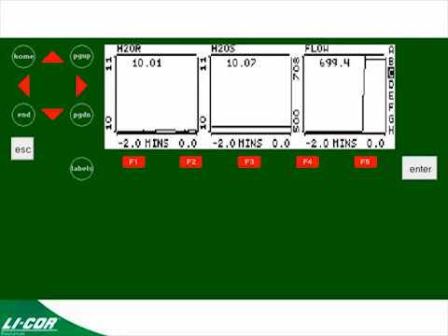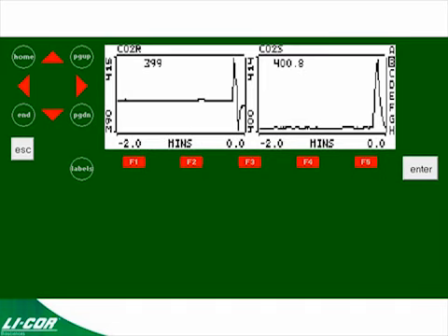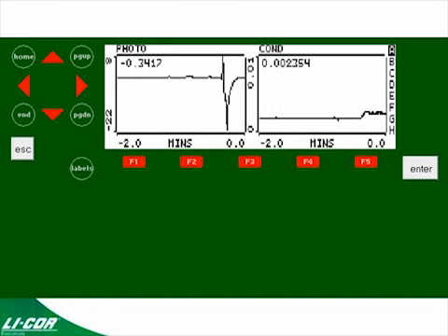I have done a quick little experiment here. You're looking at some data where the instrument was changed from a flow rate of 500 micromoles to 700 micromoles per second, and that change in flow rate resulted in a spike in the CO2 concentration in both the reference and in the sample cell. This spike in CO2 concentration results in a momentary change in the photosynthetic rate, and the problem is that this leads to instability. So we recommend using a constant flow rate and then using the desiccant to control the water concentration by altering the scrub or bypass adjustment.